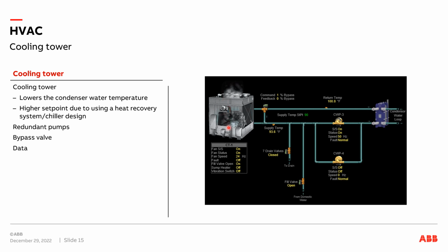The VFD also has a bypass on it, the one that we chose, because that's a real easy way to get some redundancy from the VFD's point of view. So if the VFD was to fail, you can put it in bypass mode. Bypass means the motor runs at full speed, and when it does that, you're going to have lots of fan cooling across that cooling tower.